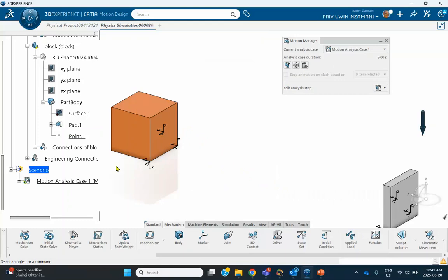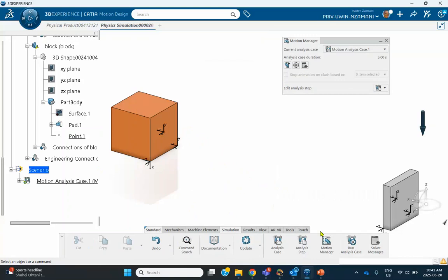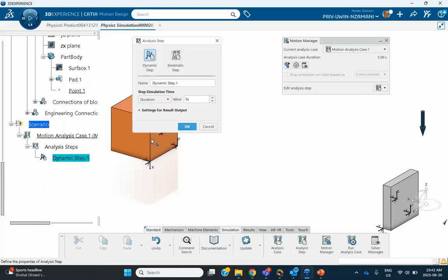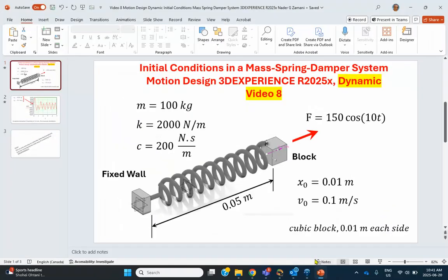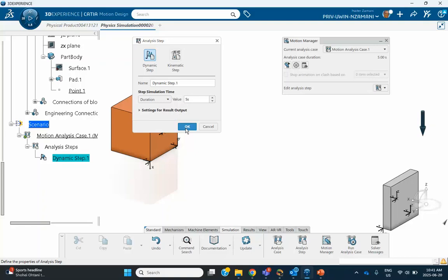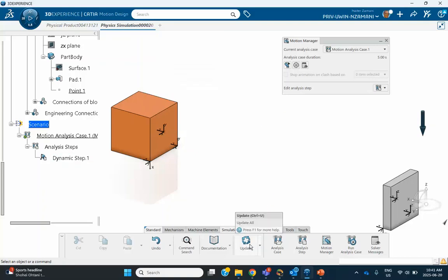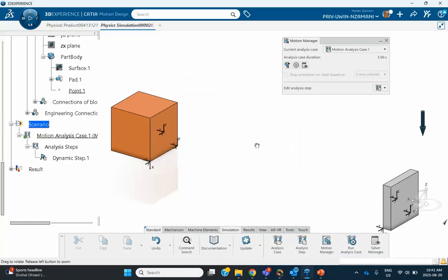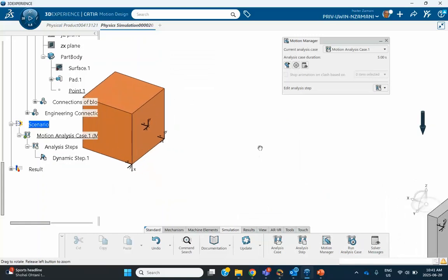And pretty much done. We go to simulation. Oh, how many seconds do we want it? Just forgot to do that. Double click. I think we want it over 5 seconds. That's the default 5 seconds. Very good. And now run it. Wait until it says succeeded 100%. And now let's go and look at the animation. And later on, we're going to do the plot.